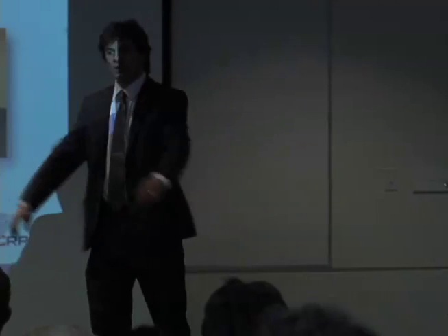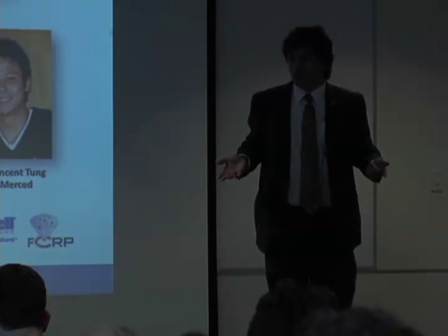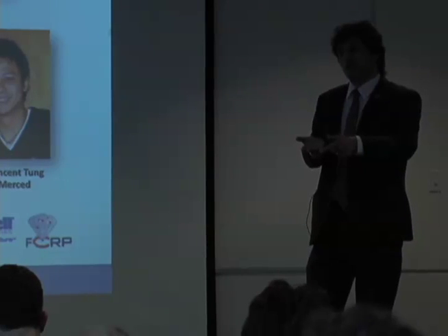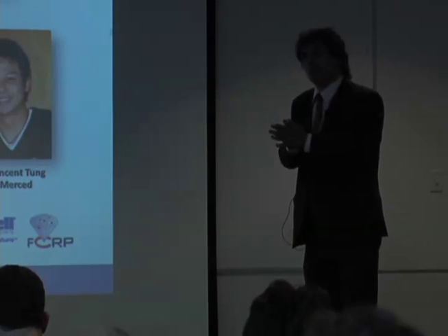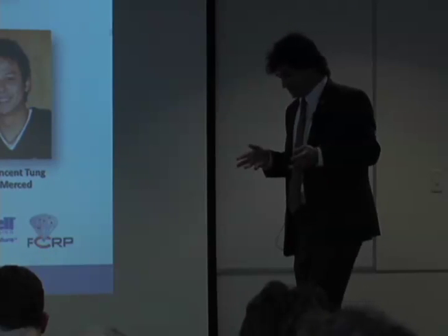What line width did you get in the laser scribing technique? Yeah, good question. So these cheap lasers are 780 nanometers. And so you may ask, what line do they draw? Well, they literally draw a 780 nanometer line. Now, there is some thermal spread. So then the question is, can you use other wavelengths of light? And the answer is yes.